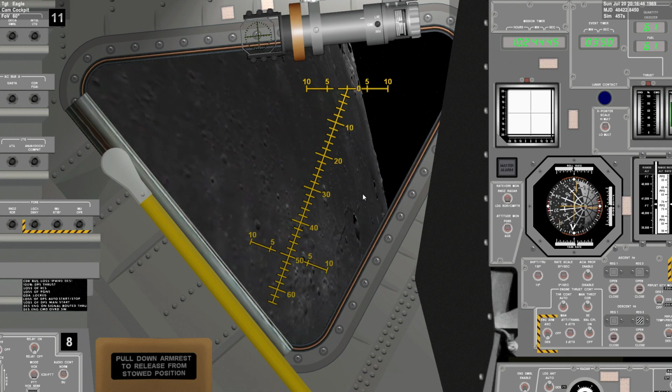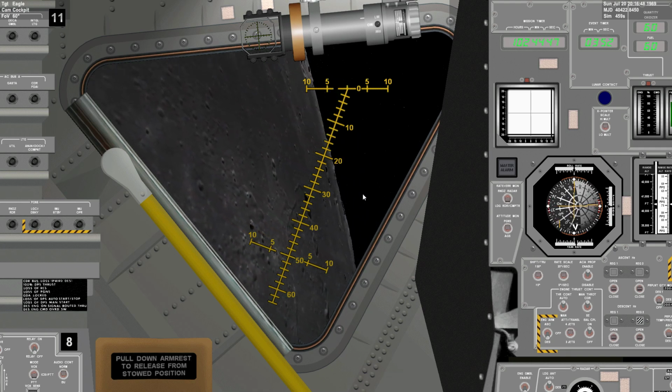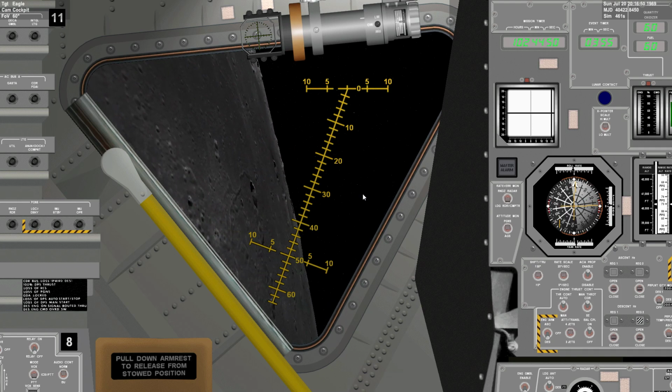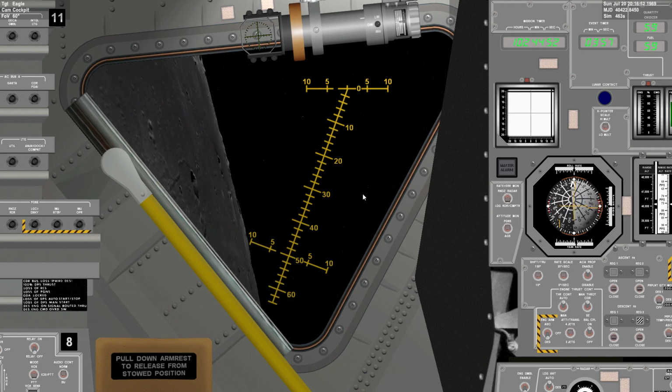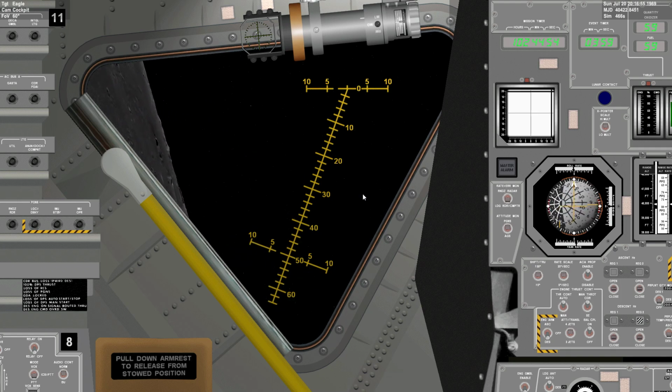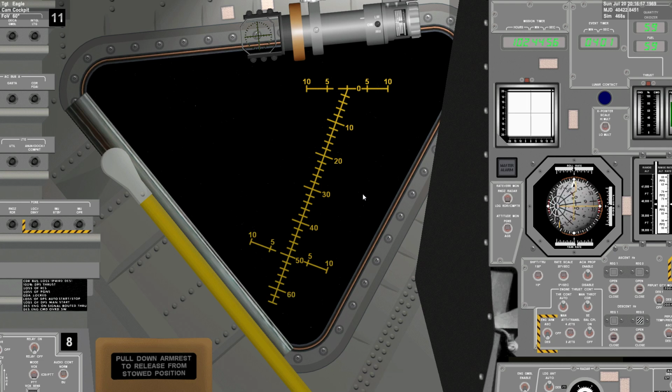So the other big difference from last time, I was having problems with random attitude excursions on the LEM, sometimes causing me to crash into the surface. I had workarounds in place to make the CDU counters not make the RCS fire like mad. Lots of sort of weird behavior, and I ended up tracking it down. I don't know why, but I know that my peripheral instructions, writing memory inside the AGC, are a little bit buggy.